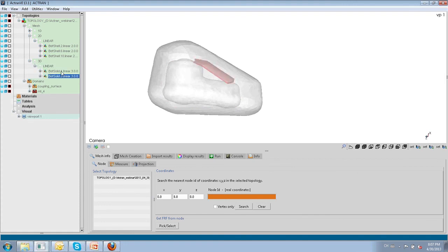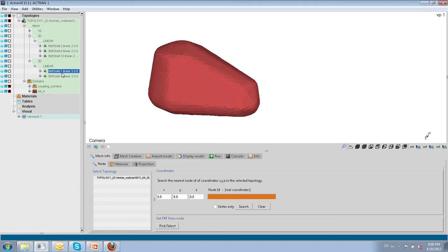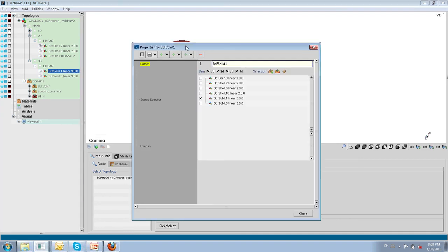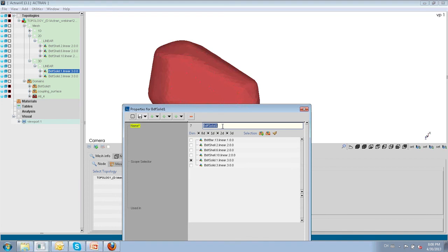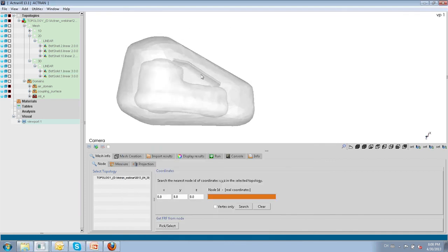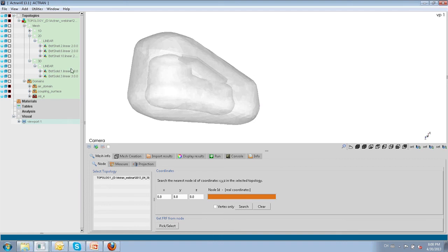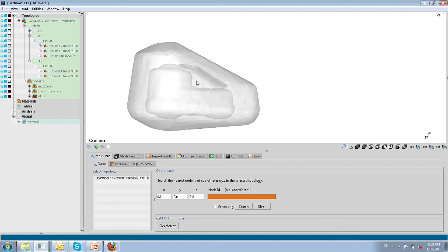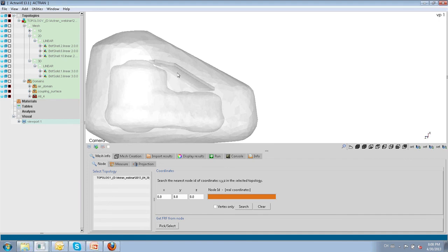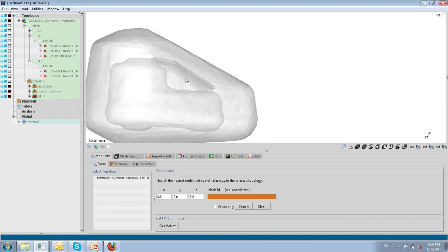And then acoustics propagates in the volume. I will create a domain on the 3D volume and call it simply air domain. Now, if we look at the mesh from the interior, the air domain actually doesn't include this shell and porous domain.